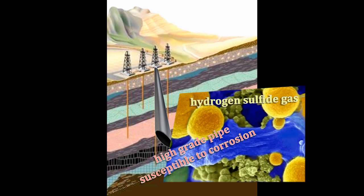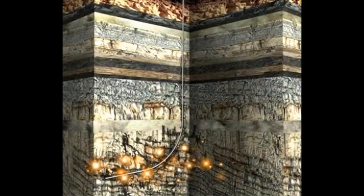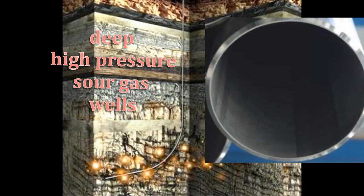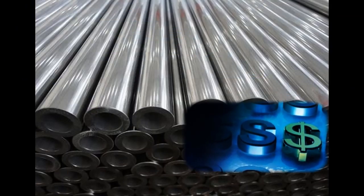For example, the presence of hydrogen sulfide gas (H2S) is particularly troublesome because H2S can penetrate high-strength steel to become brittle and lead to cracks and breaks. In very deep, high-pressure sour gas wells, nickel alloy pipe is often the only solution. Because it is very expensive, it is used only when nothing else will do the job.